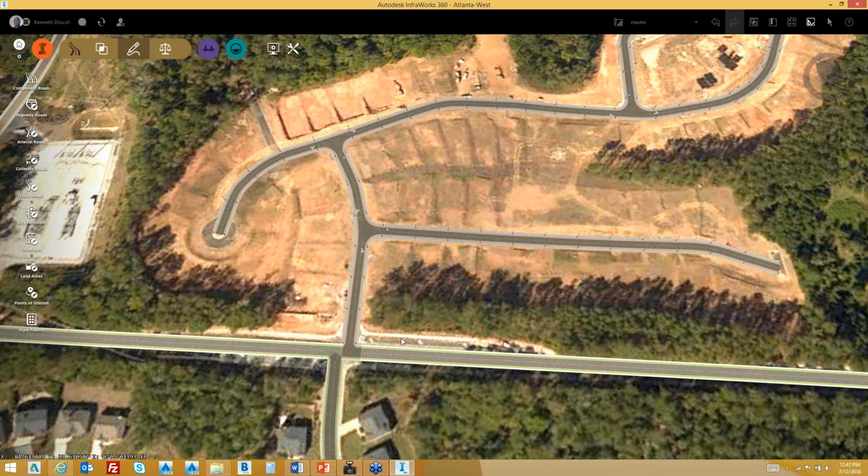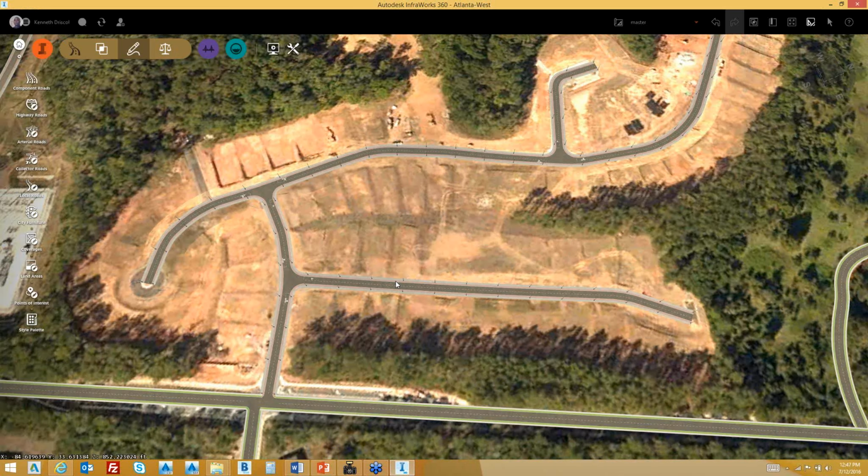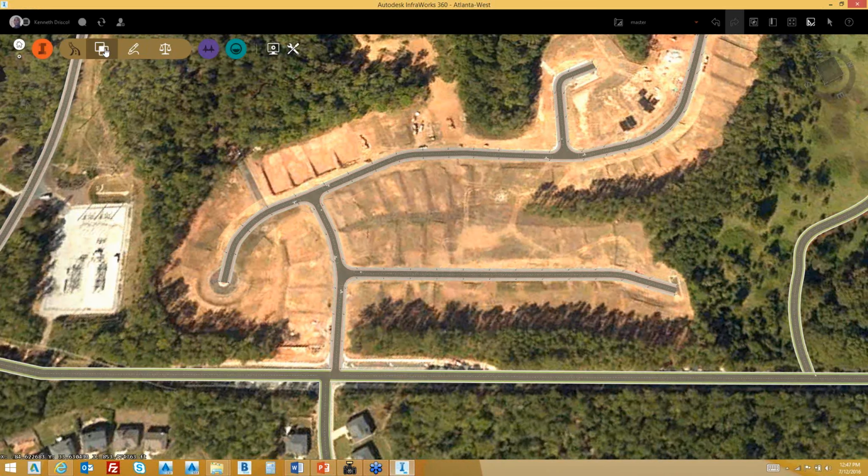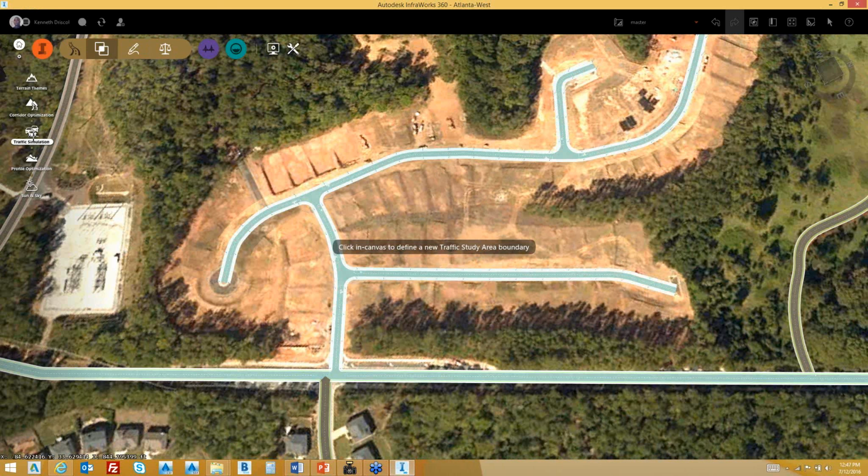based upon national standards. So one of the things that the traffic analysis allows you to do, and right here, if I go to Analyze, we have a traffic simulation. So I'm just going to pick on it, and then it highlights all my design roads. What I want to be able to do is create design roads from the ones that didn't have AASHTO standards built into them.